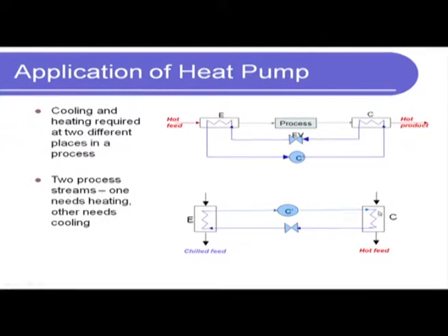Why? Because the refrigerant has rejected heat and condensed, and thereby heated up this feed in the condenser. Over here the refrigerant at the low pressure has converted from liquid to vapor, and while doing so it has absorbed heat from this feed 1, if we call it so, and as a result the feed has lost heat and it has become chilled or cold.